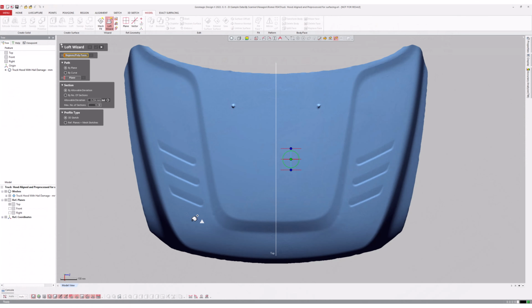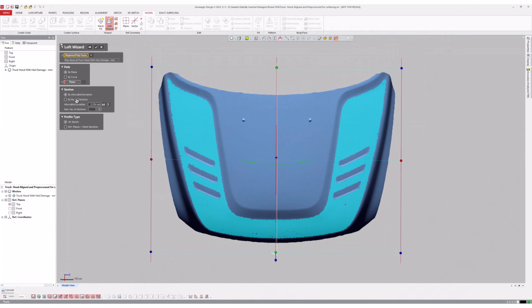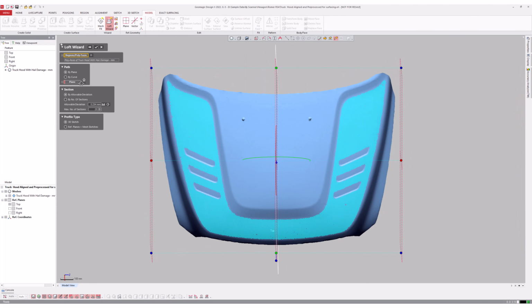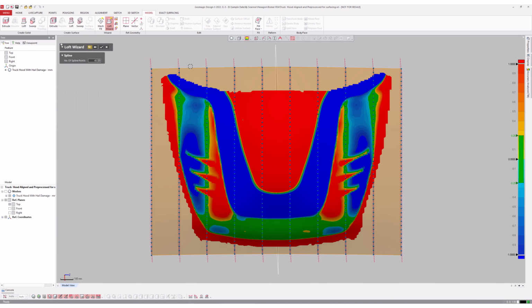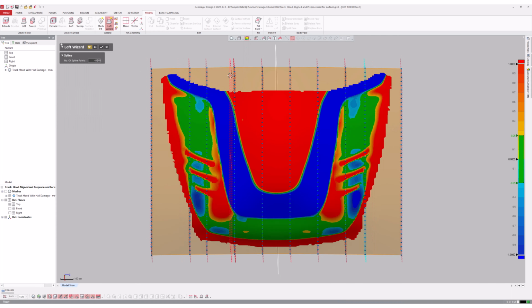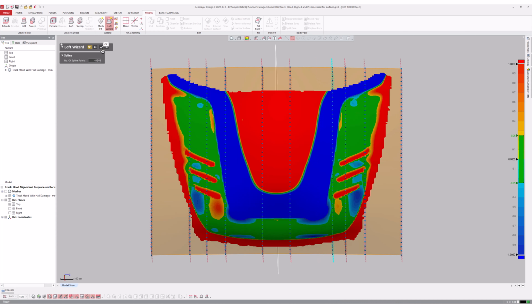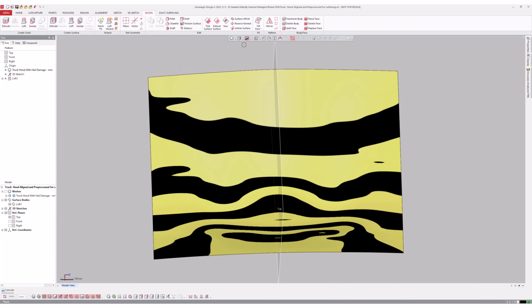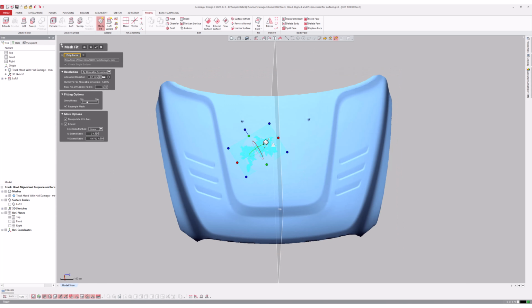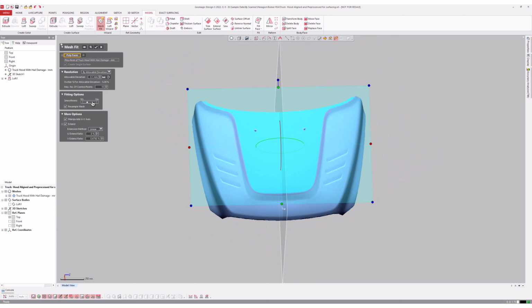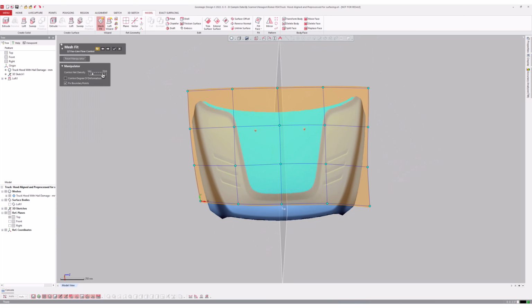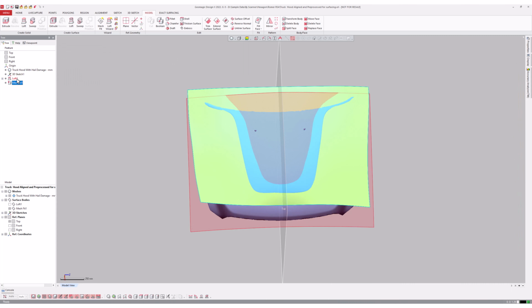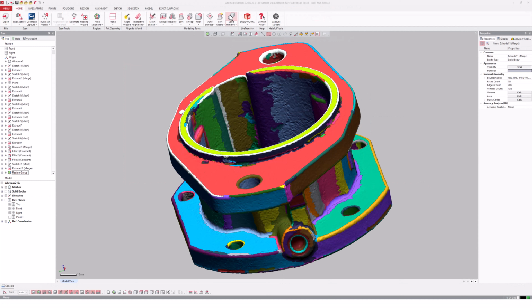The Loft wizard can create open or closed loft sections on a mesh triangle or region selection. The cross sections can be oriented and surface size bound using the control box or by selecting an existing plane or curve. The number of loft sections can be a function of the resultant surface accuracy or determined manually, as can the smoothness of the surface with a slider, and the result remains editable in major CAD packages after live transfer. This is the big difference between the Loft wizard and the Mesh Fit tool, which can create similar complex surfaces from mesh selections and regions, but those surfaces are not parametric and cannot be edited once transferred to another CAD software. Finally, the solid and surface primitives commands.